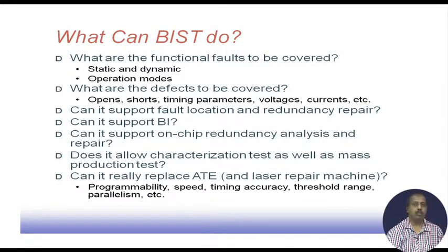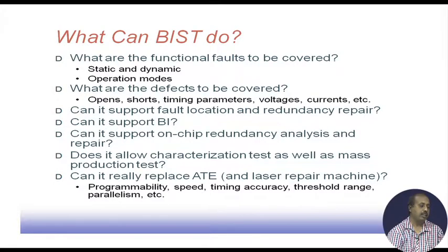Does it support burn in? Actually, burn in is when this design first comes into existence, it is kept on for quite some time, and then if there is a problem, many of the wrongly manufactured modules will die down. So, that way our yield can be improved by removing these burn in chips. So, can it support this burn in detection, can it support on chip redundancy analysis and repair? That is also important.